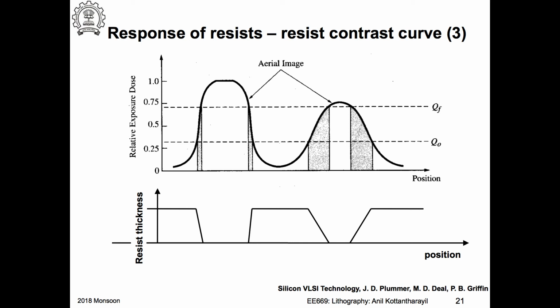meaning a lot of things happen there. Okay, so one of them is actually that the material will emit secondary electrons, so you are actually observing them. Yeah, but suppose this material is charged, so you are actually bombarded with a lot of electrons, it becomes negatively charged. So then what happens? The incoming electrons will now be deflected. Okay, so I don't get secondary electrons.